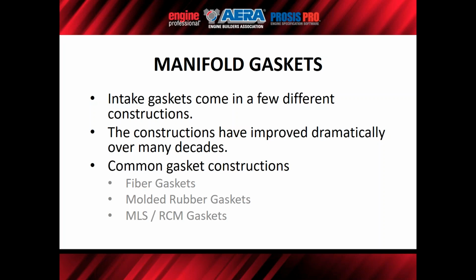The engine designs changed. They included plastic manifolds. Those plastic manifolds require a different type of sealing element, to try and accommodate some of the characteristics of plastic manifolds. So as the changes in the automotive industry occurred, the gasket manufacturers needed to develop products to match those changes.